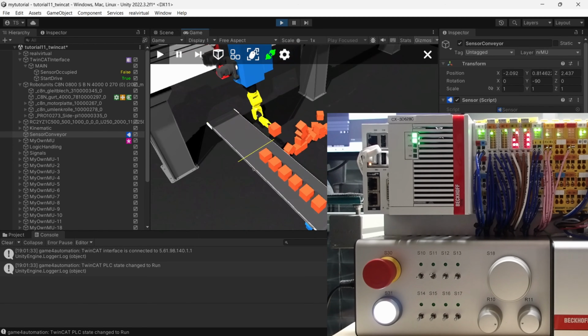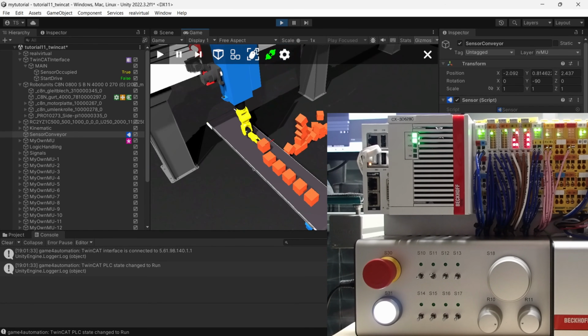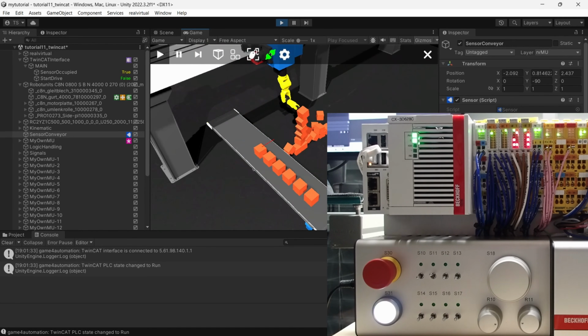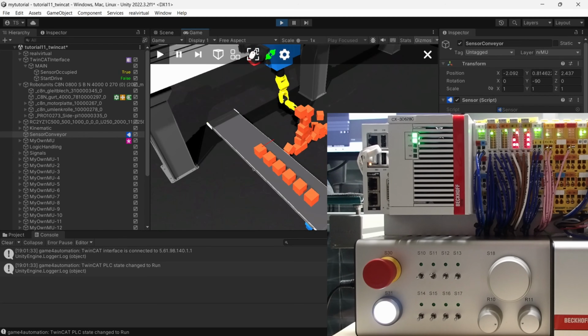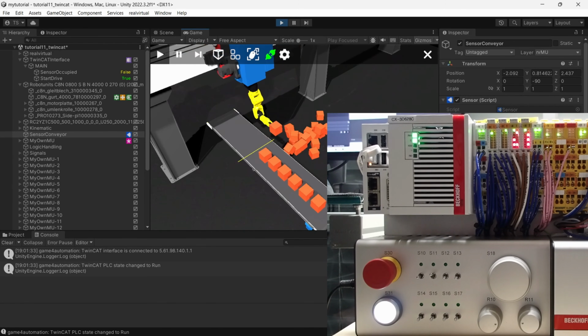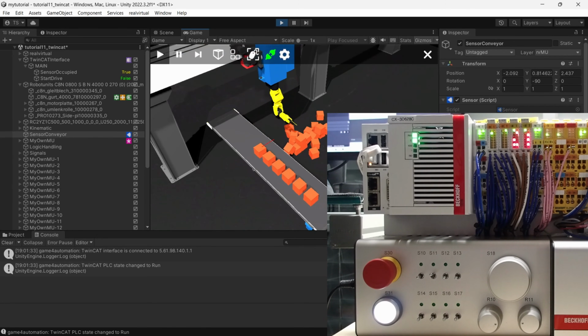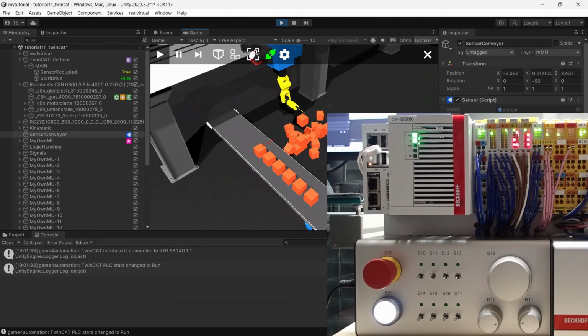That's it for today. I hope you enjoyed our tutorial. I showed you for the first time how to connect real automation controllers to the model. So basically how to import signals on the TwinCAT interface and how to connect these signals to the behavior models within real virtual I/O. If you're already a PLC programmer, maybe something hasn't been of interest for you.